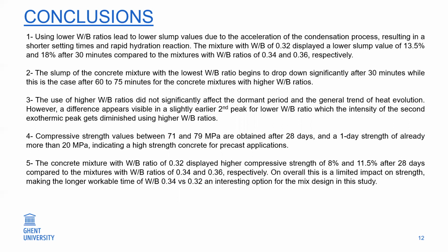The use of higher water to binder ratios did not significantly affect the dormant period and the general trend of the heat evolution. However, a difference appears visible in a slightly earlier second peak for lower water to binder ratio, while the intensity of the second peak gets diminished using higher water to binder ratio.